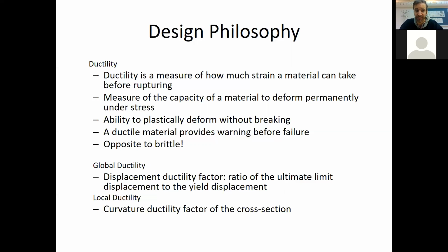which is very stiff. Glass is hard. It's difficult to deform. But once you deform it, it kind of explodes. It collapses. So even though it's hard, there is very little ductility in it. So it's stiff, but not ductile. Of course, an example of a construction material that has high ductility is, for example, steel, which is much more like chewing gum.